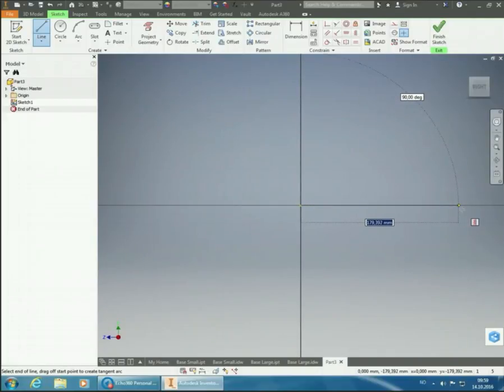And it's supposed to be, let's see, it's supposed to be 137 millimeters long on that one. And we have to remember to press our Tab button to get the padlock in place for the dimension. And then we click Enter. So then we've got a start for our part, and we're going to continue on after the break.